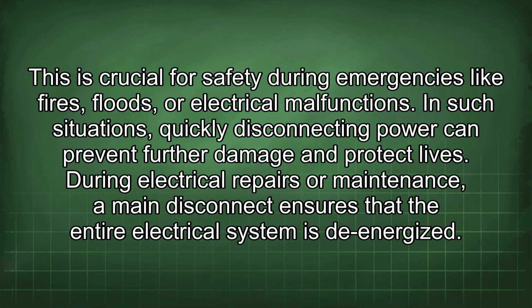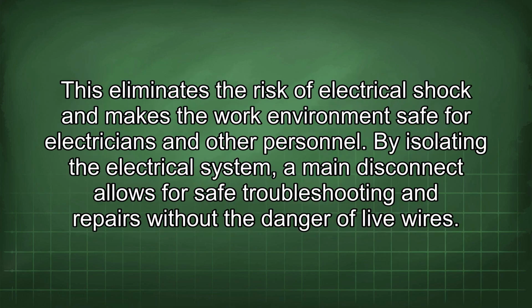During electrical repairs or maintenance, a main disconnect ensures that the entire electrical system is de-energized. This eliminates the risk of electrical shock and makes the work environment safe for electricians and other personnel. By isolating the electrical system, a main disconnect allows for safe troubleshooting and repairs without the danger of live wires.